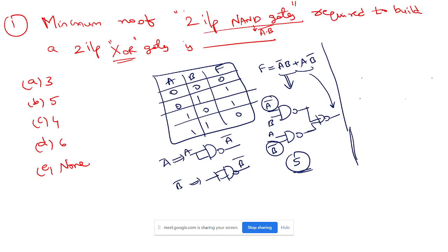But there is one more way. What is that? If you look at another format, let's say this is M1, this is M2. We have already seen this actually extensively, or you can come to my YouTube channel. There we talked about SOP form, canonical SOP, canonical POS, simplified, very much simplified. Anyone can understand. So F can be written as either M1 plus M2 or M0 plus M3 whole complement.